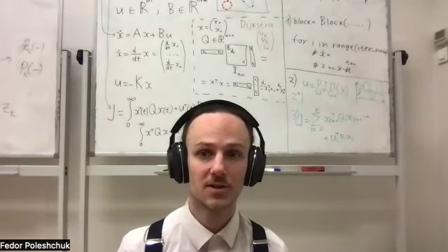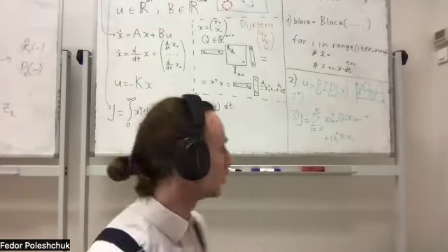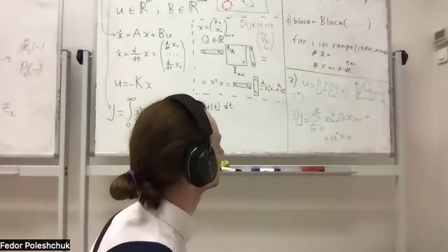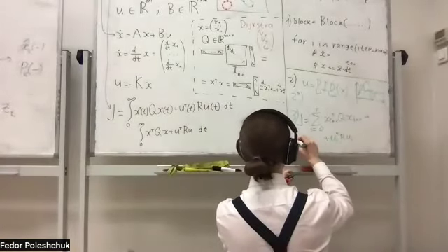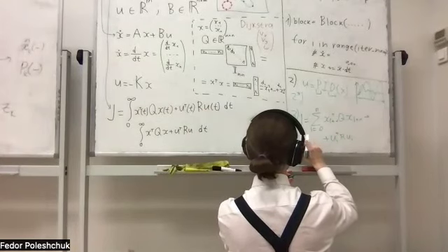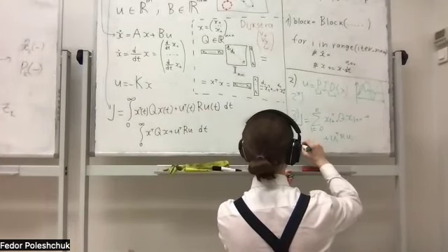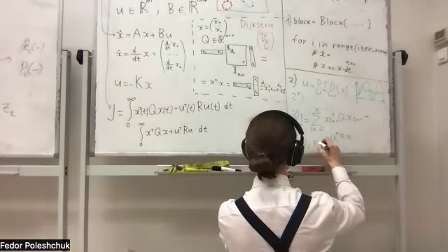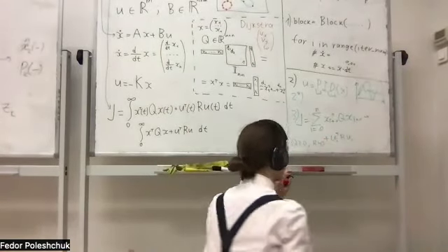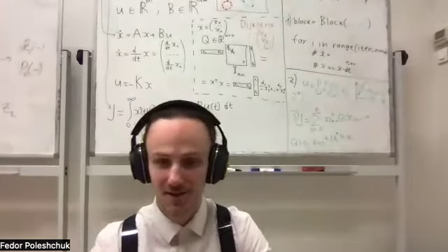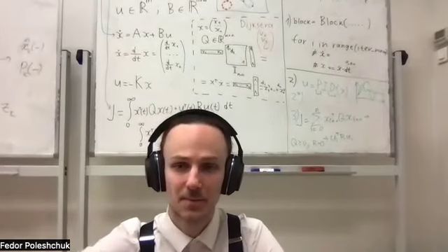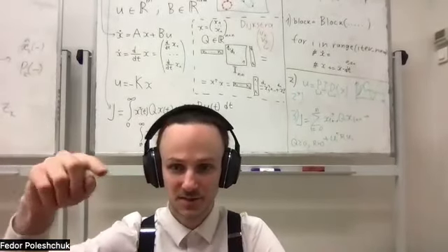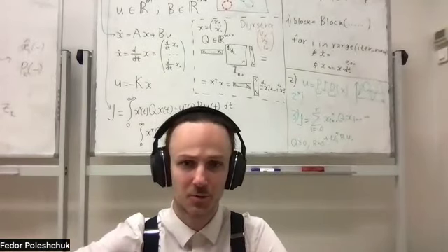The next time we will talk about the derivation of the controller, and we will talk about the characteristics of those matrices. We will require the Q matrix to be positive semi-definite, which could be written like this. And the R matrix has to be positive definite for our results to make sense. But that's for the next time. By positive definite, I mean that for any vector x, x transpose times R times x is greater than 0 for non-zero vector x.